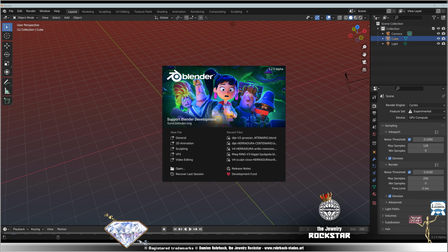Right, so now or later, but let's do it now. Let's create a material here. Just create a new material for the bezel, and let's call it white gold. Maybe my follower will do that in silver, but generally wedding rings are made of white gold. Okay, so this has a material now, the gemstone also. Okay, so now let's go back to the bezel, because obviously we can't have all that covering the gemstone. Doesn't work like that. Edit mode, Alt A. Now we are going to take the top part here and delete these faces.